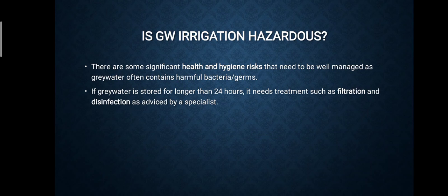Is grey water irrigation hazardous? Some significant health and hygiene risks are there that have to be well managed, as grey water often contains some harmful bacteria or germs or any other microorganisms that cause threat to the growth of plants and other things. And again, if grey water is stored for more than 24 hours, definitely it needs some treatments like filtration and disinfection so that it can be used for any valuable sources.